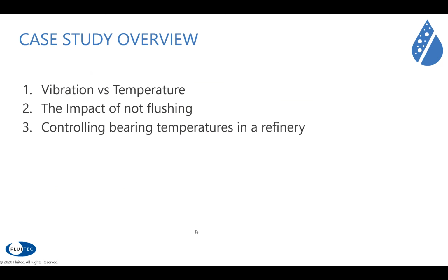This is a case study where on the left side you can see a point where they changed the oil. And within 1 or 2 days, as you can see on the X axis, it is 4 days, within 4 days, you can see that on the low, medium and high pressure side of this compressor, all the temperatures are increasing in the region of 90 till 100, 110 degrees C. And with this, repetitive peaks are coming up, and you can see that even the medium pressure side is also increasing. When we stopped this compressor, this was the result when we looked at the actual bearing on the medium pressure side.